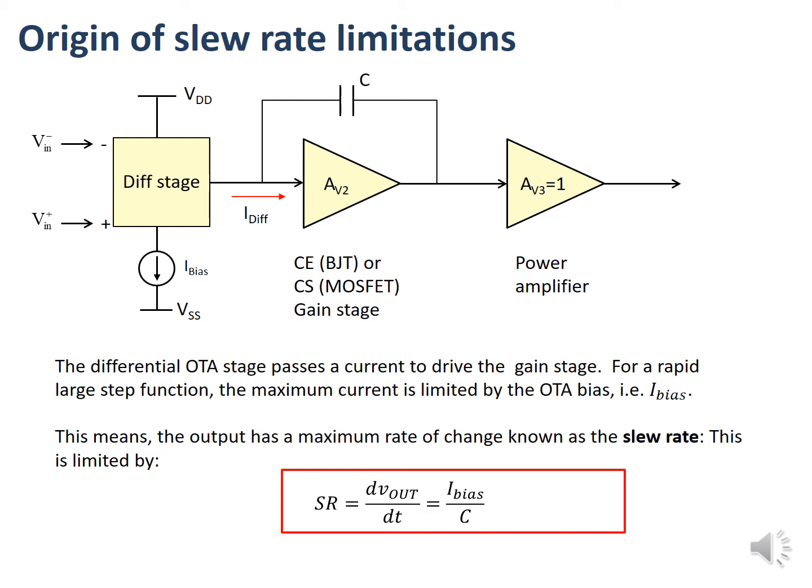What happens in that differential stage is those signals turn on the gates of the transistors, and that then allows a current to pass down through the chain inside those differential stages. And there's simply a limit with how much charge, how much current the power supply can pass down through those transistors. That's really the limitation: the ability of that differential stage to pass current.